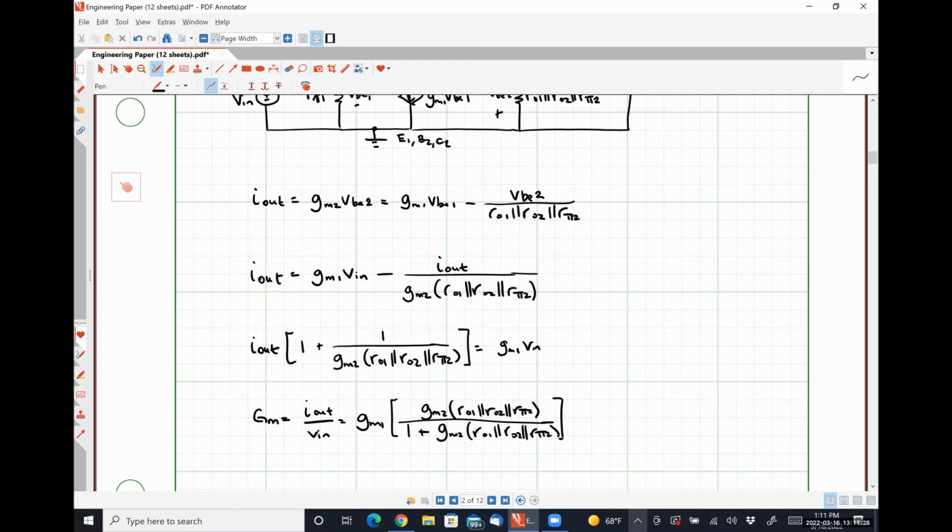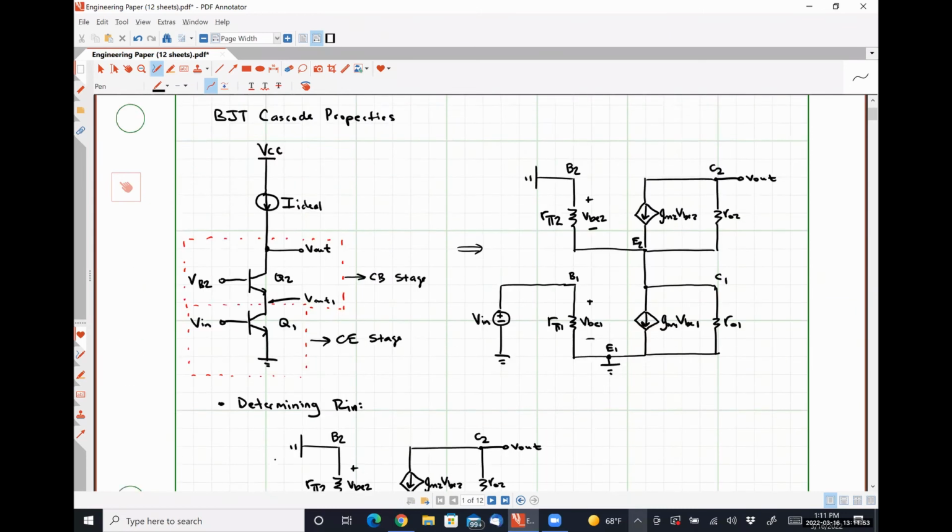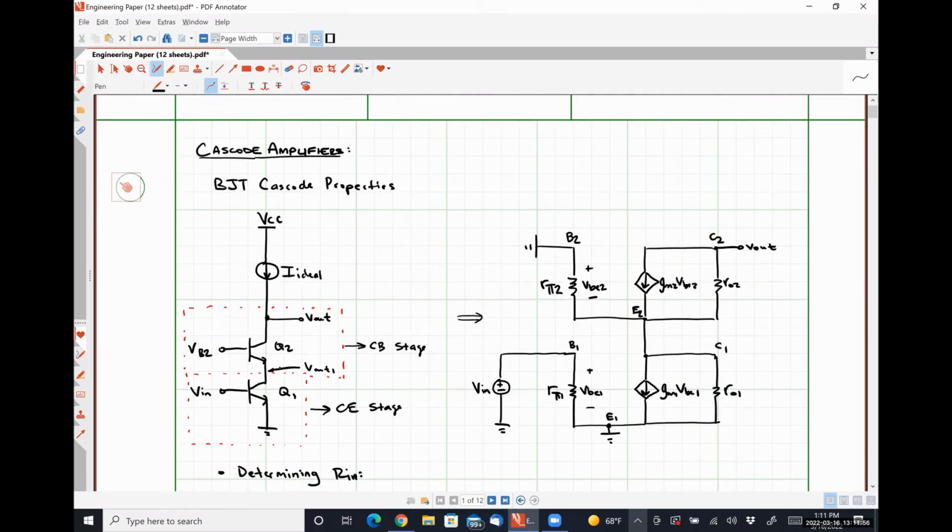Okay. If we are building an integrated circuit, all of our BJTs have to have the same early voltage. Literally cannot happen any other way on an integrated circuit. And we know that from our original diagram, the amount of collector current flowing through Q2 is going to be pretty close to the amount of collector current flowing through Q1 because their betas are going to be the same.